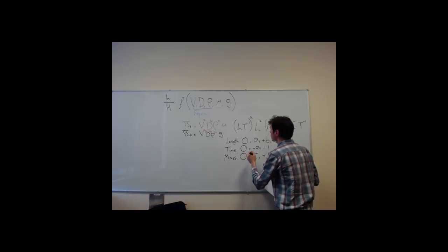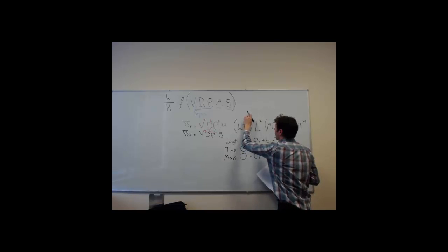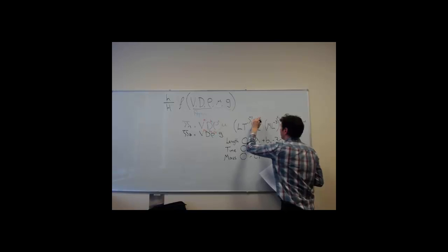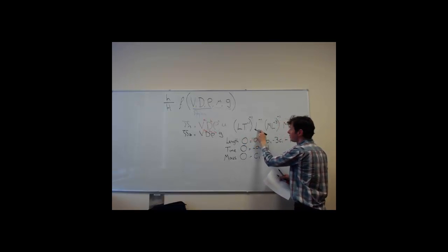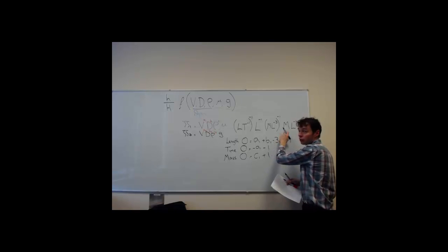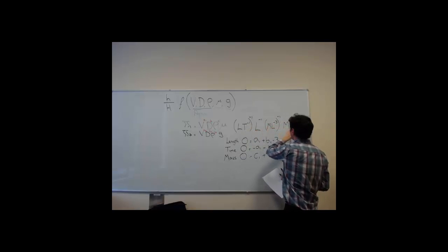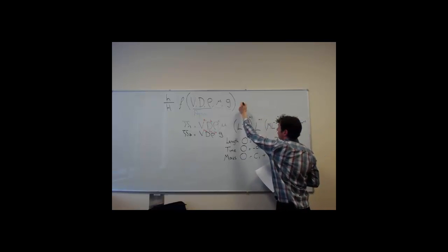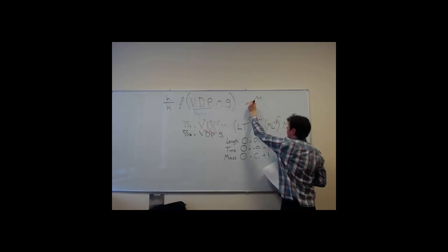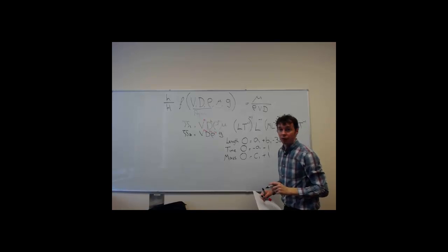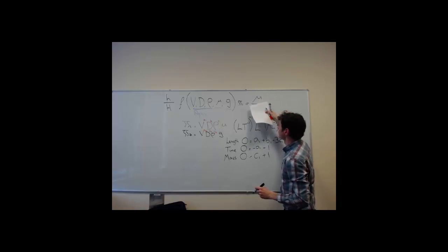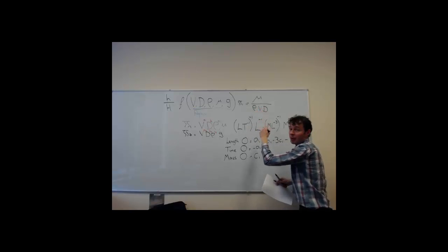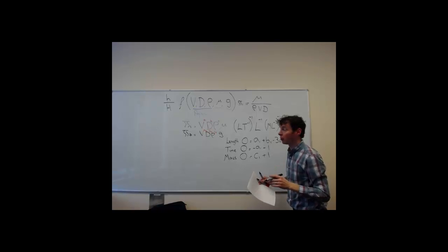Okay? So we can also scrub those out. Remember we have velocity, diameter, density, and viscosity. These three to the power minus 1, that one's been left alone. So our fundamental dimensionless group is equal to that, which may look familiar. We call it the pi1 group. So we've got dynamic viscosity divided by this term here. If we put all the dimensions back in, they'll all cancel out, because we've done it properly.